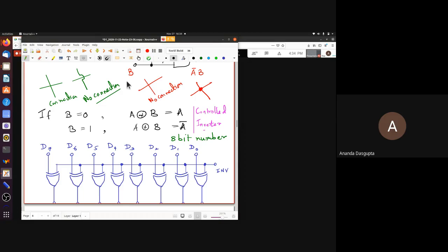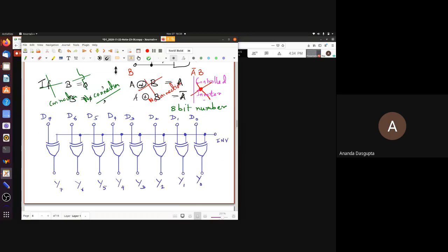In other words, in analog, no connection actually has to be shown, that is, by showing a bump. In digital, connections have to be explicitly shown by putting a blob. So that's a standard convention for drawing, and this is important to remember because otherwise it might confuse different situations.